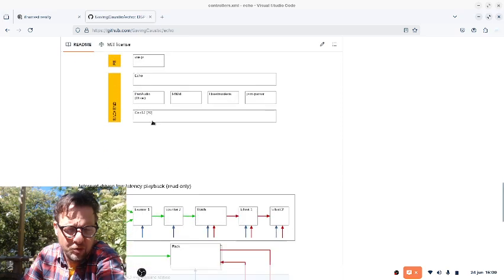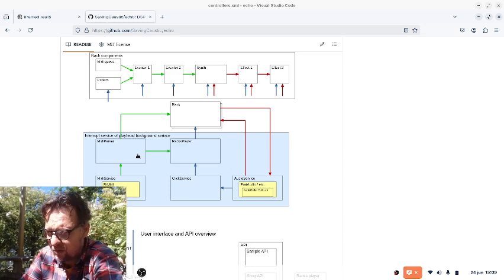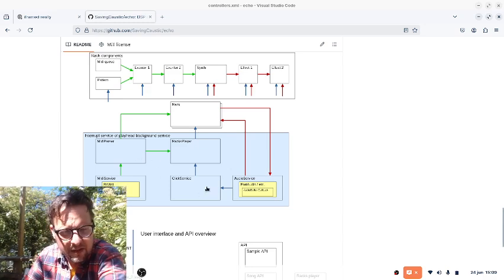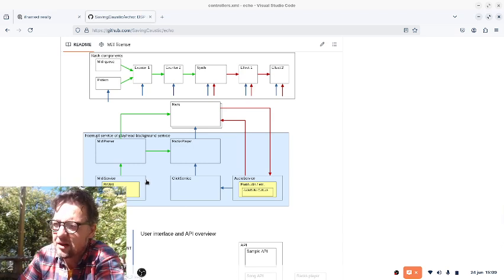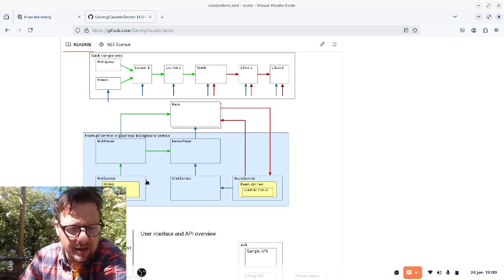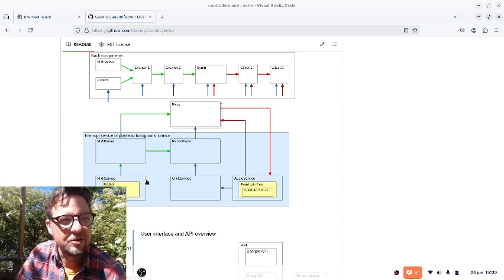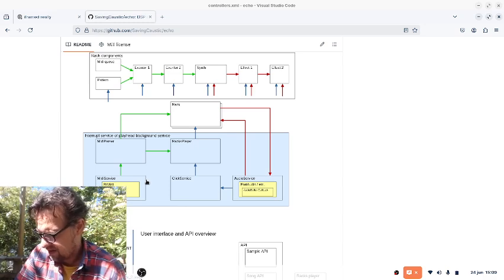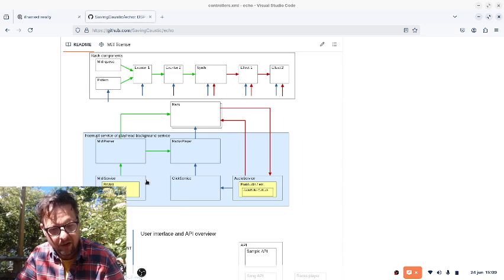If we move on to how this is all put together, you have an interrupt service where the audio buffers require more information to render output. Being interrupt driven, you don't want any I/O going on, like file reading and writing. I think that's a good discipline to have. Outside the interrupt routine, you have pre-buffering for the audio input and output.